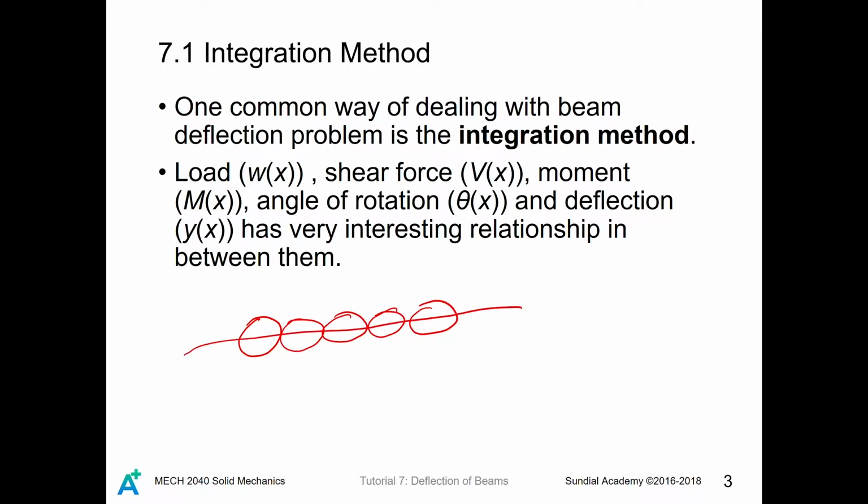Those marbles respectively represent the load, the shear force, the moment, the angle of rotation, and the deflection curve y. While we go through different kinds of proof, you will see how those properties inside a beam, or the shape of the beam, are interrelated to each other.